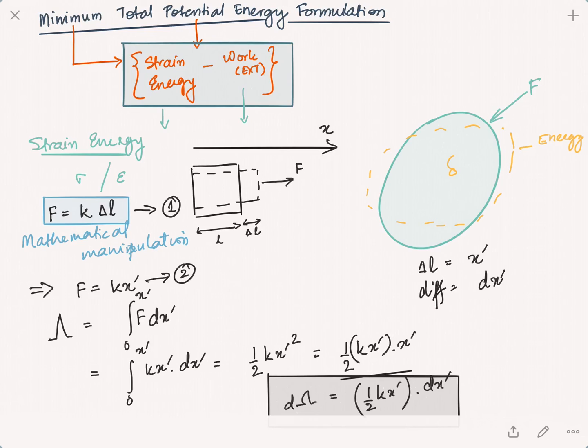So if you now go back to the original steps that we were looking at for a finite element method, then you may remember, or look back in your notes, that the final step before which we can formulate the Ku equals F equation for linear finite element analysis is always setting up equilibrium.